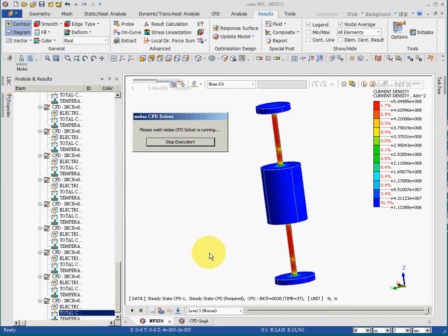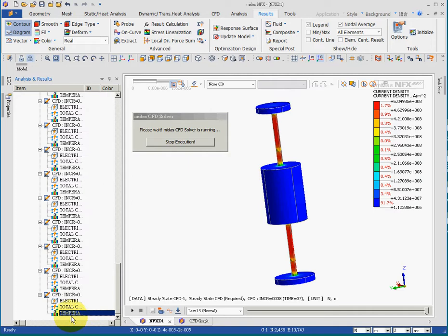And resistance equals resistivity times L over A. Resistivity is a material constant and length of the bar is constant. Therefore, the larger the area, the smaller the resistance. So you can see that here the larger area gives you the lower resistance and this is higher resistance, so they are different. And we can see the temperature difference.